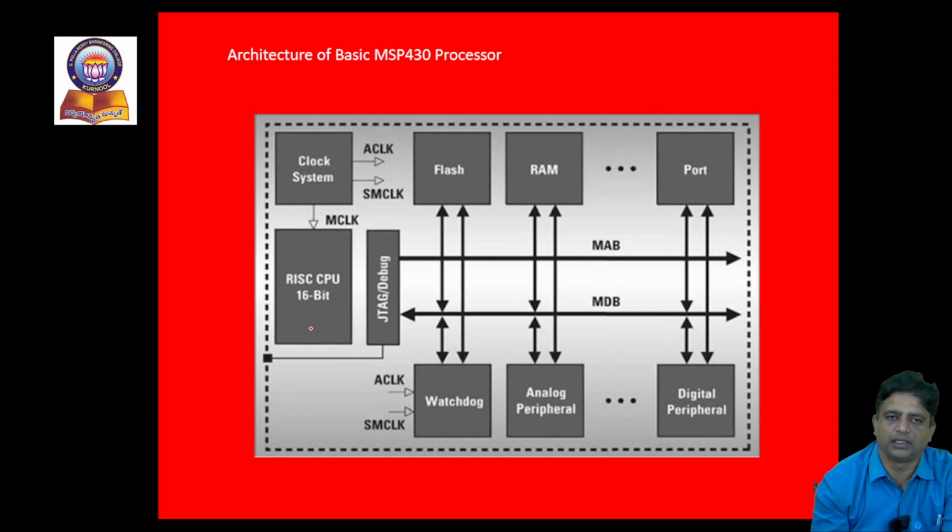Actually, MSP430 runs on a clock frequency of 16 megahertz to 25 megahertz. The maximum frequency will be provided by the master clock, and it is directly given to the CPU. Along with this, there are inbuilt provisions for dumping the programs, and connections through external peripherals. We have some more arrangements in the setup, like analog to peripheral connections, flash arrangements, IO ports, and interrupt arrangements, and all these provisions are given to the MSP430 processing architecture.